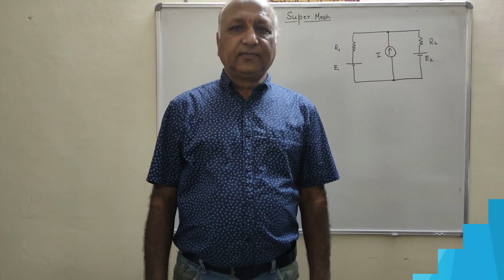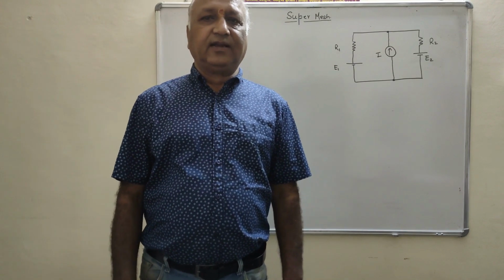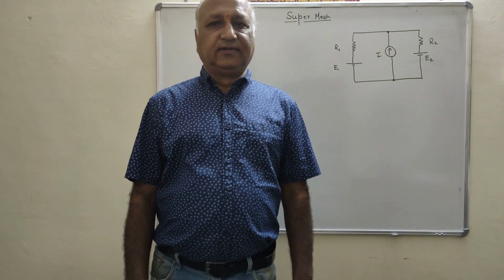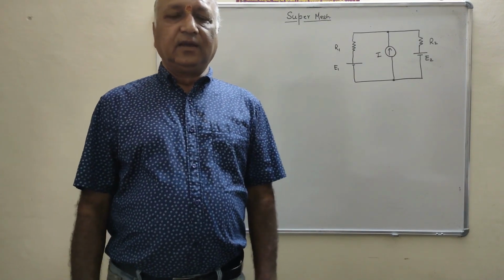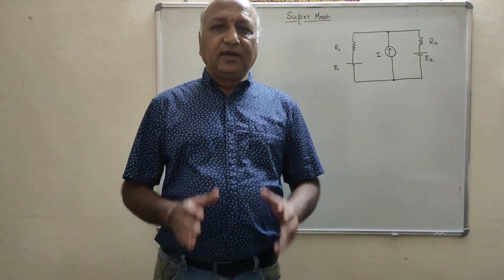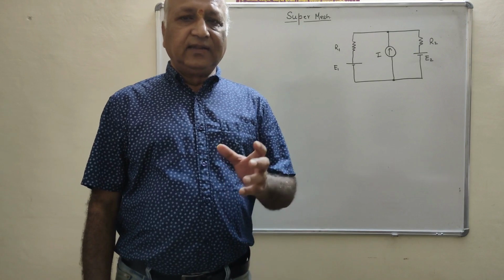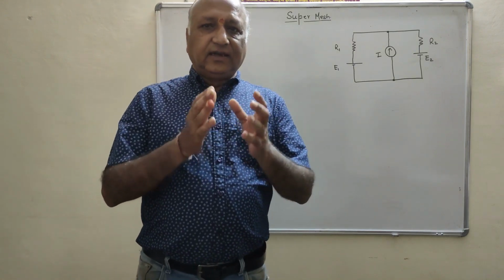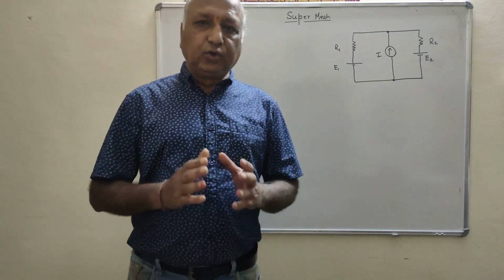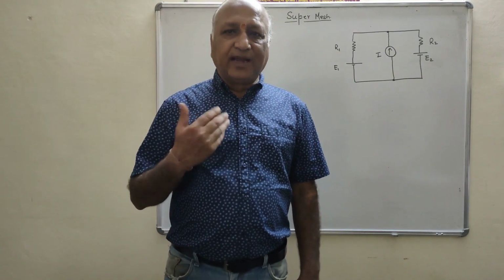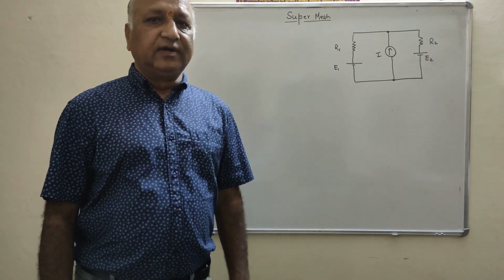Hello students, in the last lecture we discussed mesh analysis and nodal analysis. Today in this lecture we will discuss the super mesh. It is different from mesh analysis because here there is a current source which is common to the two meshes, and mesh analysis cannot be directly applied in this type of network.